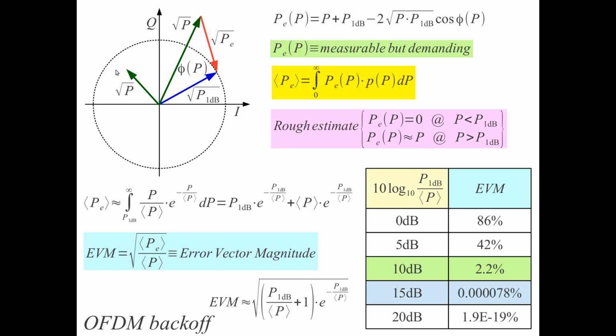So we have small distortion inside the circle, and this small distortion can be compensated by the digital predistortion. But there is nothing we can do outside this circle, because when the requested power is way too large, this power cannot be supplied by our amplifier.